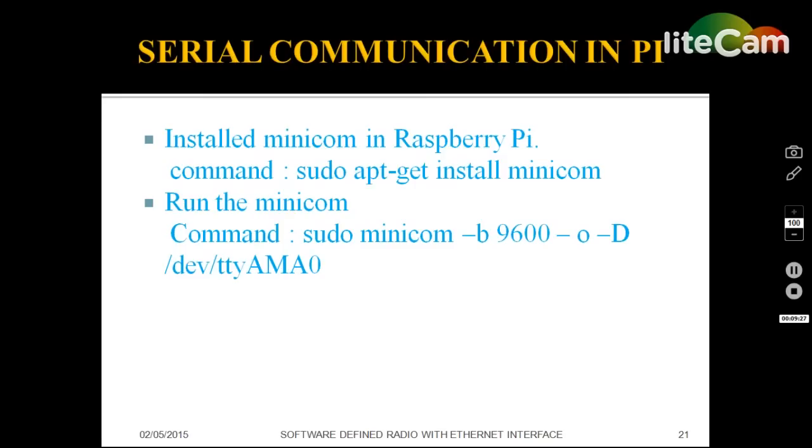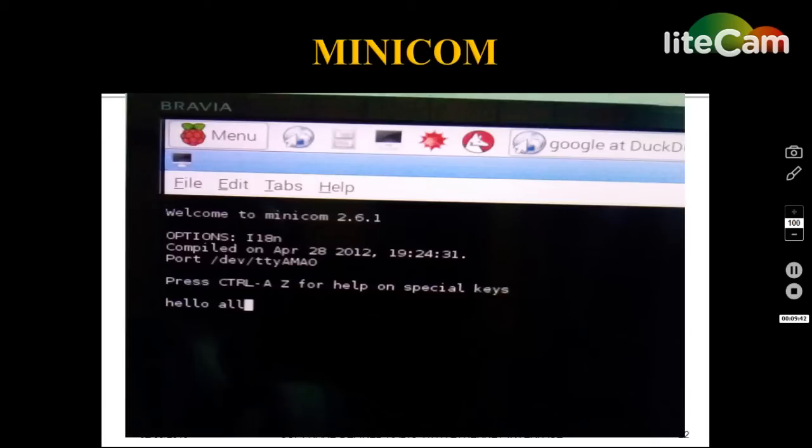In the Raspberry Pi, we have serial communication using USB and also using serial pins. If we are using the serial TTL pins, then ttyAMA0 is the device. This is a minicom terminal.